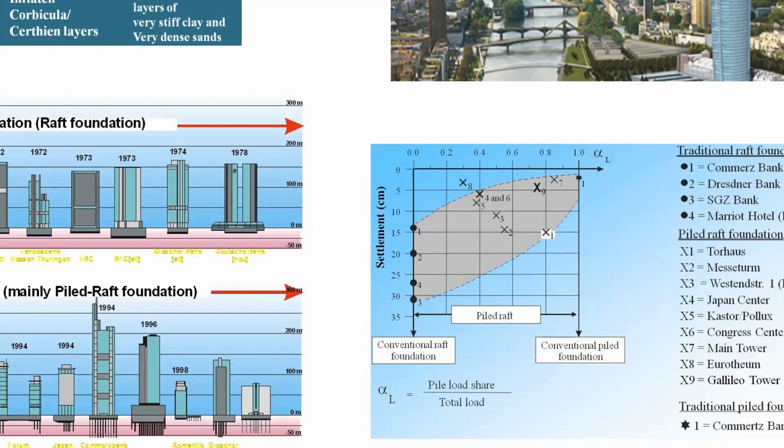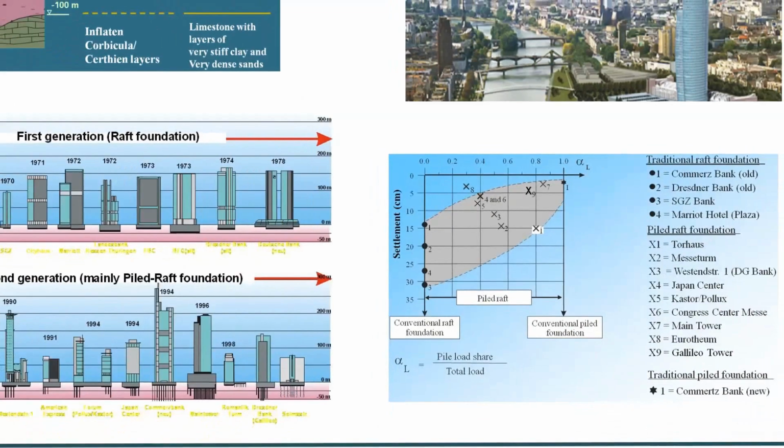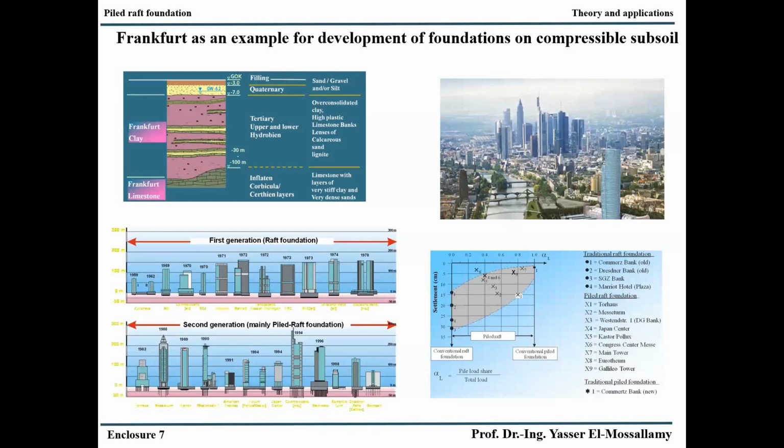And for such huge buildings and huge loads, we cannot consider settlement and differential settlement as in ordinary structures. We should check it case by case, and really we can say there are no limits. Most important is actually the performance of the building, and this is what we have applied successfully in Frankfurt clay.